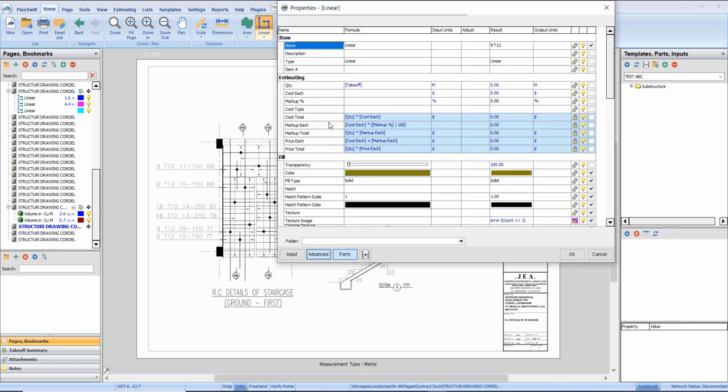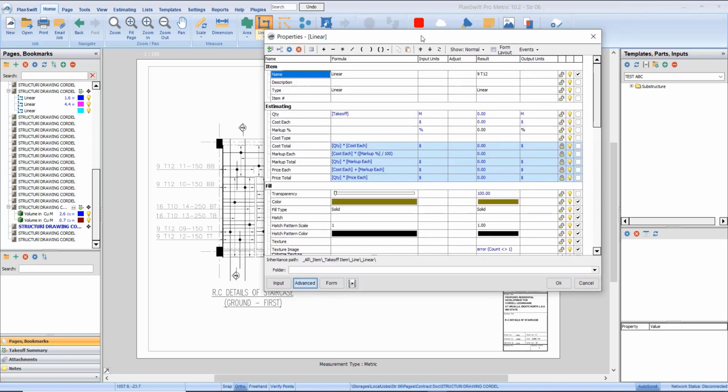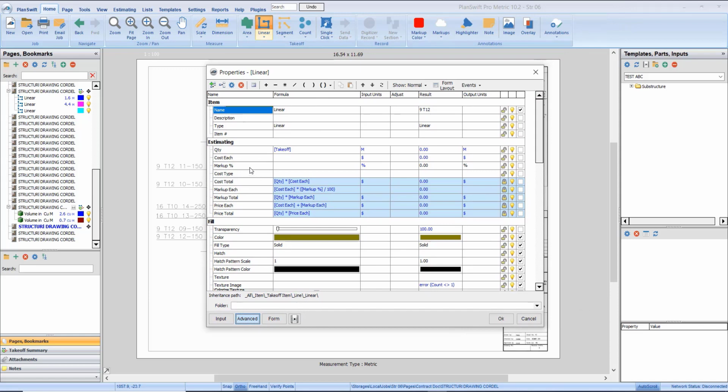and then I go to advanced, and from your advanced, let me bring that down a bit. You can see that I have my quantity takeoff in meter, just like I've said. But there is something we need, because I want it to be easier for us. We can do all of our conversion within this very section, and if we're able to do that, we can have our reinforcement either in kg or in tons. But for me, I want to go straight to have every one of my measurements in tons.